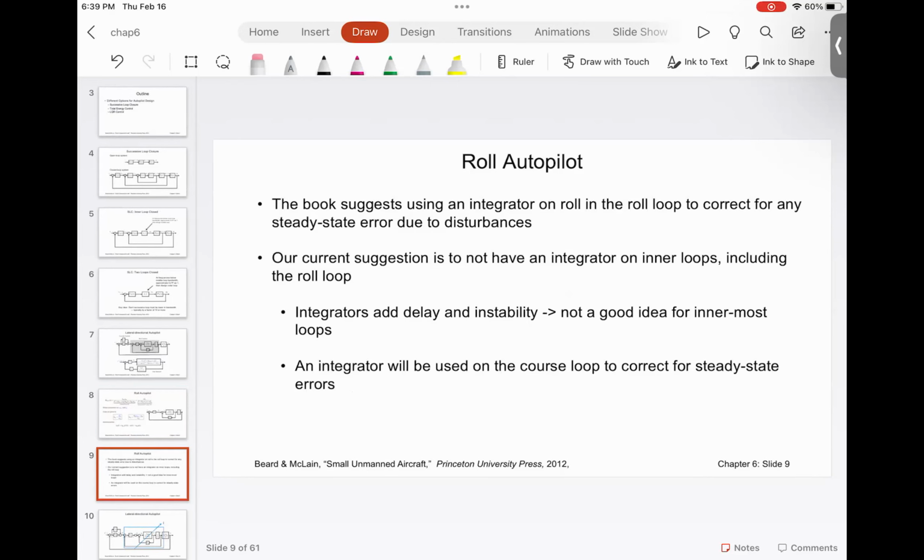the behavior. Again, the point which I was trying to say is that the integrator, if you read the book, is there, but basically the integrator is not used in practical application because of the windup. If you have gain scheduling, the integrator is not needed, and the integrator could add delays and could give rise to instability.